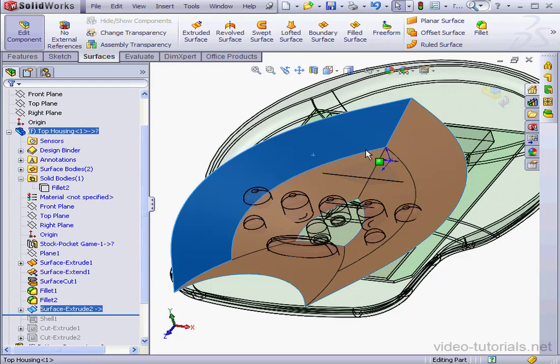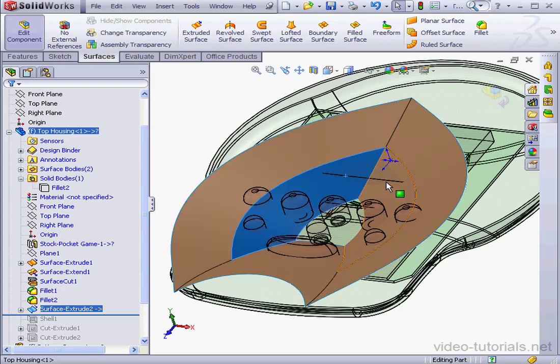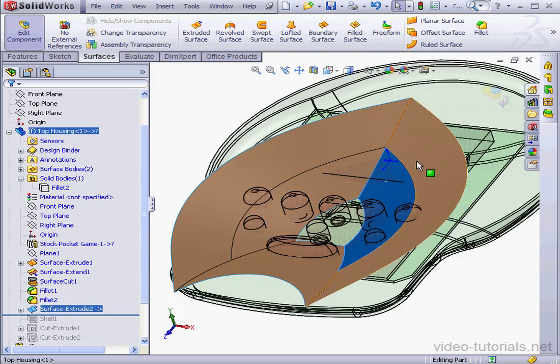The surface we created has different segments. This is the surface we're going to be using for the trimming procedure in this lesson. It's a good idea when you can to use a single continuous surface as your trimming tool. It's much less likely later on that you'll end up with errors. Having said so, let's go ahead and make some changes to our extrusion.